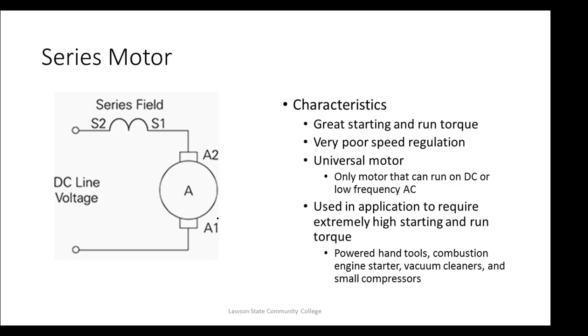And you can hear that sucker change speeds when you move it across something, right? You're up here vacuuming and you're on a hard floor and you go onto a carpet, you hear it slow down. But why is it slowing down? Because it needs more torque. So these guys create a ton of torque. They got crummy speed regulation. As soon as you load them down, they slow down, but they slow down in order to create good torque. Great starting and run torque. Very poor speed regulation.